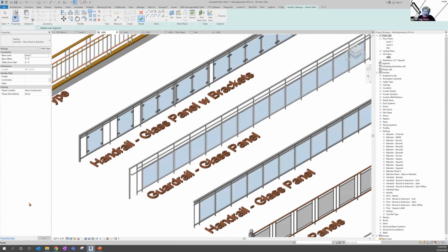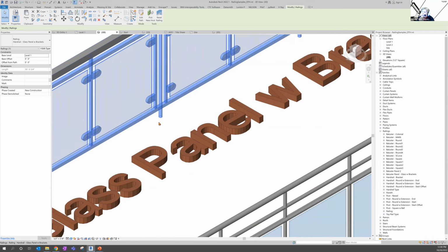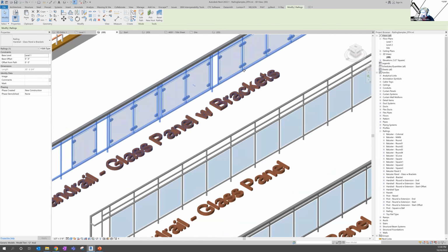So by putting this in here, I see, well, 4 foot, I've still got a huge gap because of the way it wants to place these other balusters in the center. But 4'6" looks like that would be what I would want to go with, so that I don't have, we took the post that was down on every one of these and shortened them to the 3rd rail. That sounds bad. The rail number 3. And then by adding a post, it looks like 4'6" is a good break if I don't want to have the post coming out down on all of them.